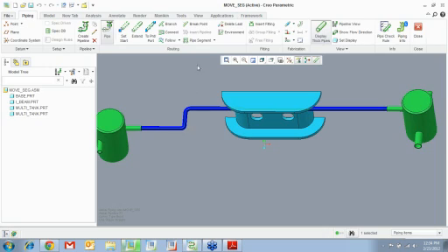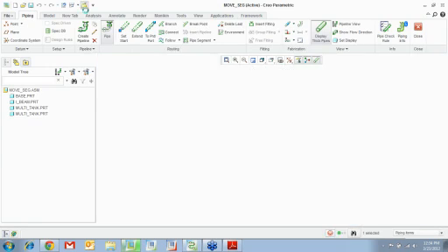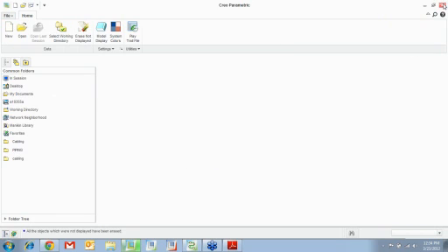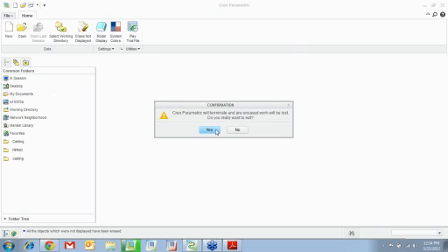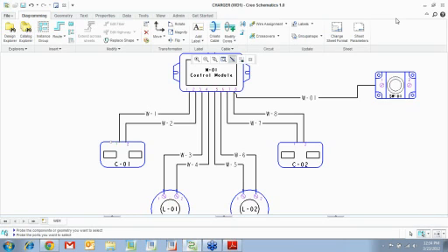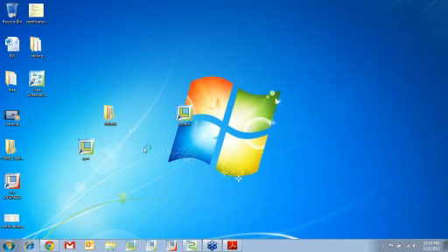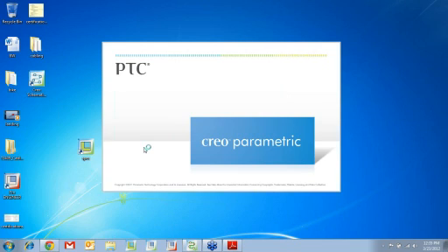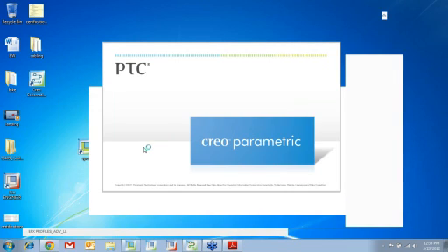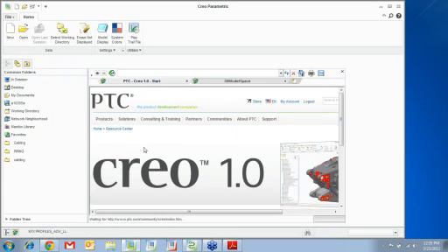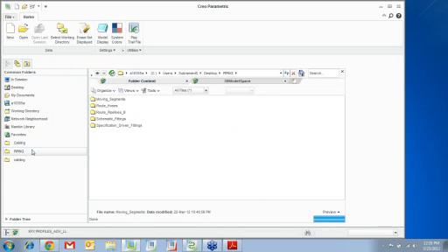Okay, so it's really, really simple and really easy to do. So the next thing that we have after we do this is to do a spec driven piping. Let's do spec driven first, and then we'll do a schematic driven. In a spec driven piping, what I do is I basically go ahead and set up the specs for a certain pipeline. Say what type of fitting to use, what sizes I should use. So once I set up these things, my usability, ease of use is very high.